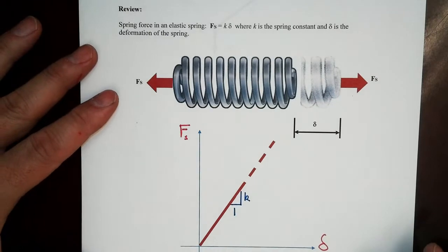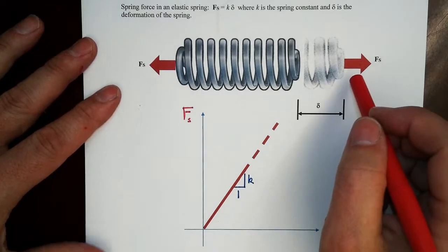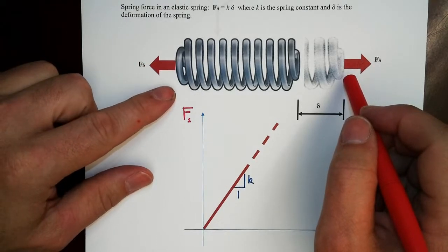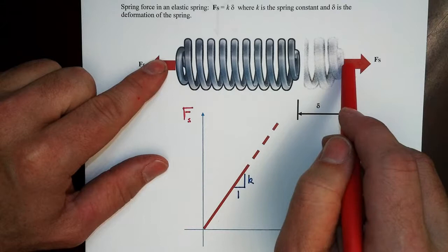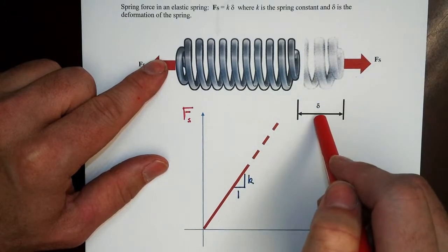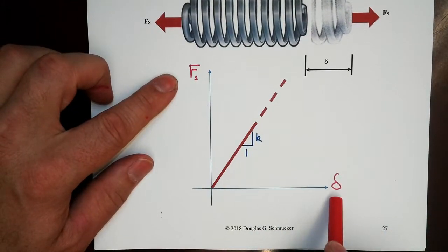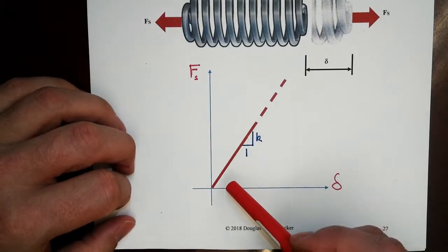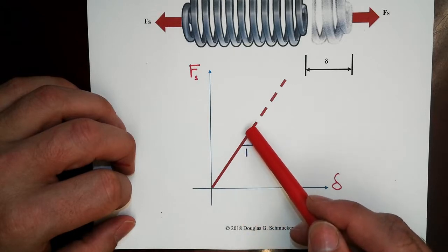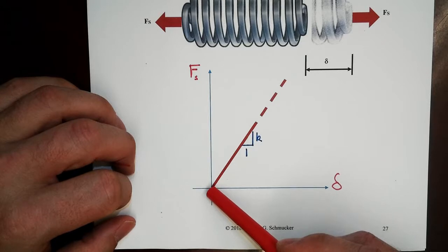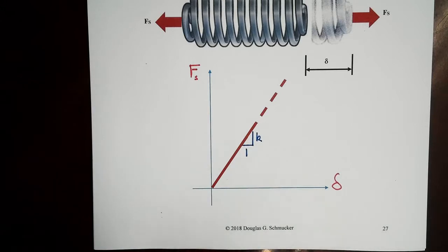Right, so the big thing to remember from your physics experience is that one way to model flexibility or stiffness in a system is by looking at, well, if we pull on something, how much force corresponds to how much the elongation is. And if we plot that spring force and that corresponding elongation, what we find in a lot of systems is that they are linear in their variation, and when we unload, they go back to no permanent deformation, and the slope that describes that relationship between those two is the spring constant.